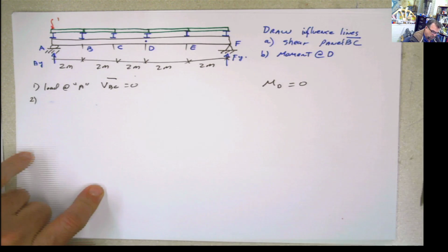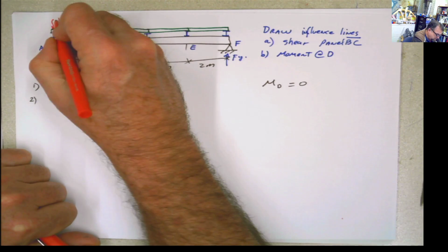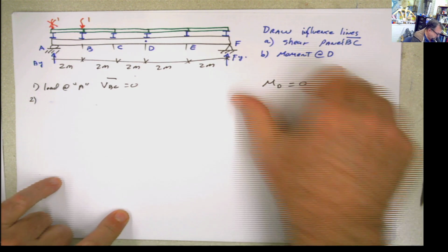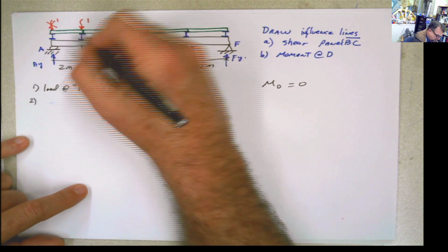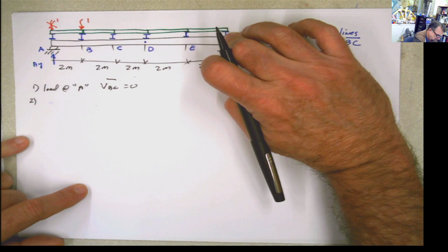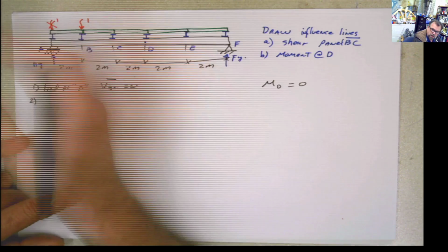So second. Now let's move the load. It was here, and now we are going to put the load there. So the load is not at A anymore, and the load is at location B. It's the same thing that we did before. You just calculate the reactions first. Summation of moments at F equals 0. Why at F? Because I want to calculate AY, I'm working with this side of the beam.